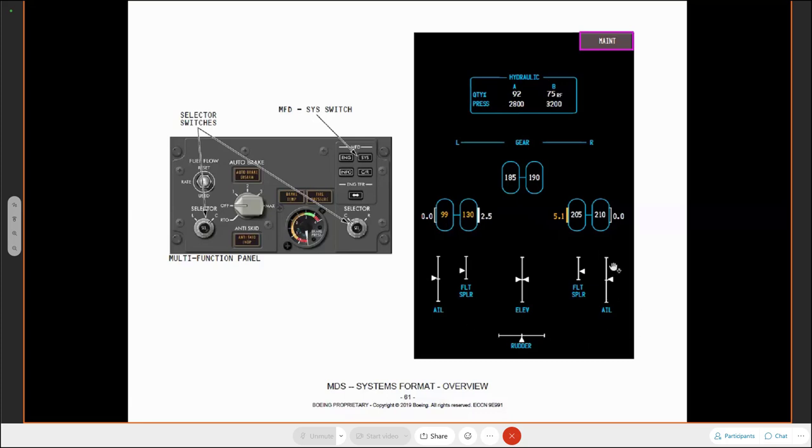This indication here, I always refer to this because it's very similar to the 787, as Dr. McCoy's medical bay. It looks like on the Starship Enterprise in the medical bay, Dr. McCoy's medical lounge, when people were dying or something like that in an episode, you used to have these triangles that went up and down a scale. This is what these are doing. These little triangles here are going up and down these scales. This is all to do with flight controls. So our ailerons, elevators, rudders, and on the MAX, the flight spoilers. Don't forget the spoilers on the MAX are all fly-by-wire, controlled by the electronics unit.